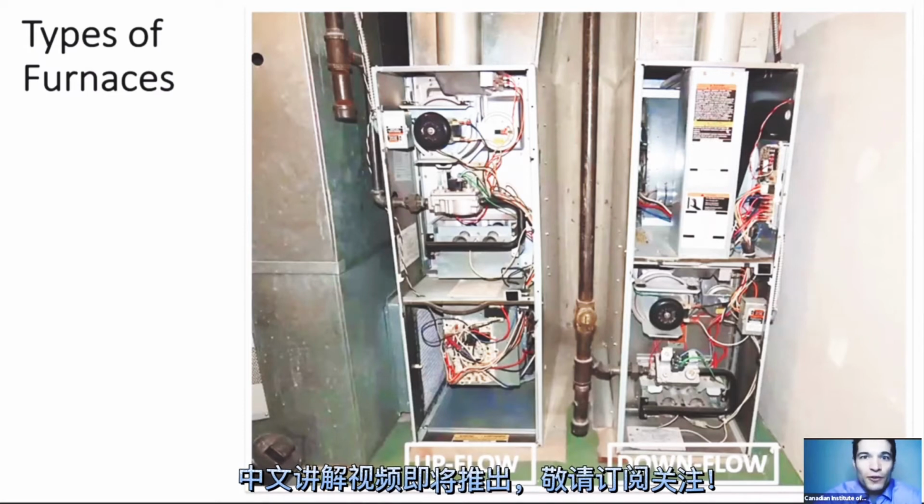If you hear any squeaking or rattling, that should be a sign that some servicing is required. And if you smell anything burning, or, as we're going to talk about in a little bit, gas detection, those are additional tools you want to bring to the job site to make sure you're doing a decent inspection. A lot of home inspectors will carry carbon monoxide detectors. They may take the detector outside, calibrate it, and then go to the exhaust vent or a heat register and place the monoxide detector there to see if there's any sort of integrity loss with the unit, primarily with the heat exchanger.